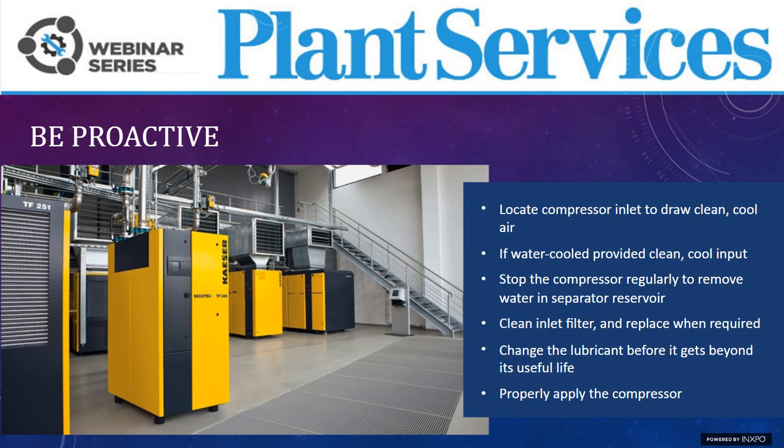So locate your compressor inlet near clean, dry air. For water-cooled machines, you want to provide clean, cool input. You want to stop the compressor regularly to remove water in the separator. Also, you want to make sure you have a clean inlet filter. And like we talked about, change the lubricant before it gets beyond its useful life. The last point here is to properly apply the compressor. I can't stress that enough.